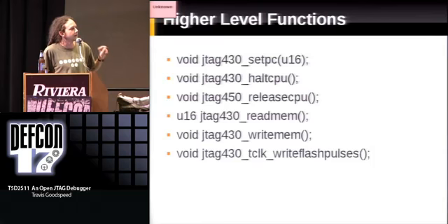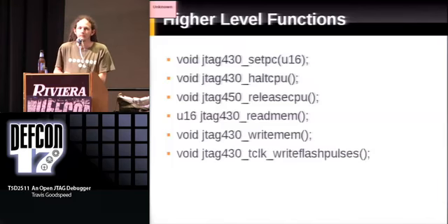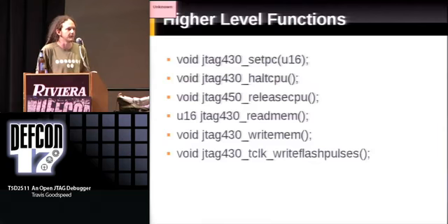It's also worth noting that writing flash memory is very different from anything else that you might do over JTAG. On most chips you have to send a clocking waveform, and it has to be of a specific frequency within a particular tolerance.